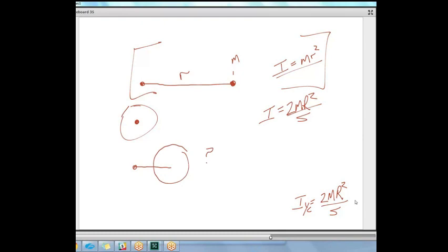What do we do then? Well, we could go through and do a lot of integration. Yeah, right. What we'll actually do is total up the two of them. The total I value for this is the I value for spinning it about its centroid, plus the consideration of the length of the string we put it on. And that is the parallel axis theorem.